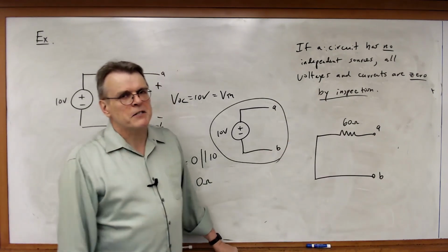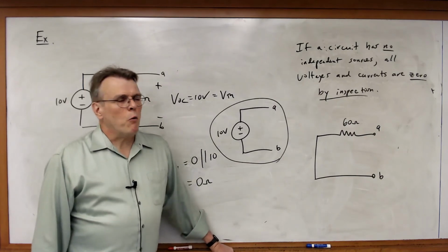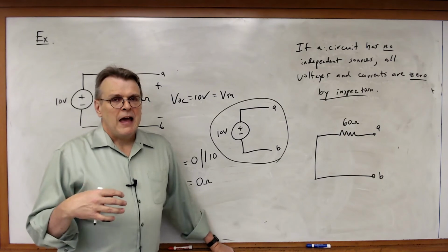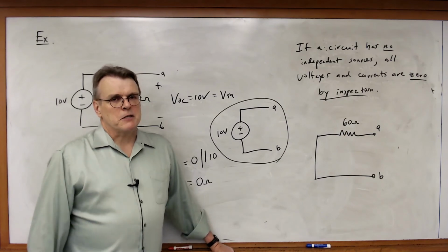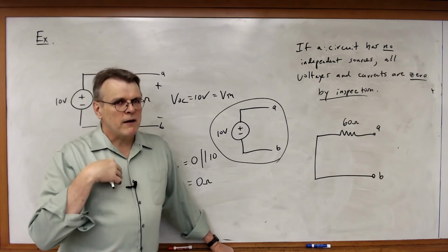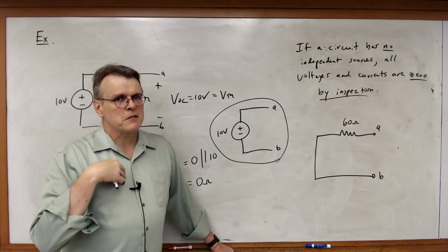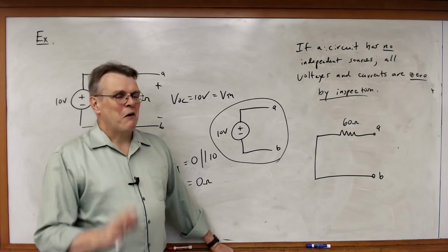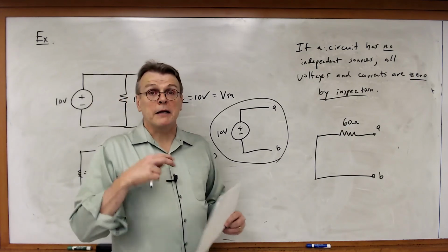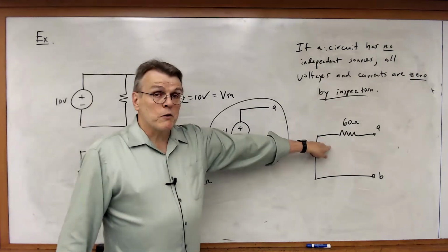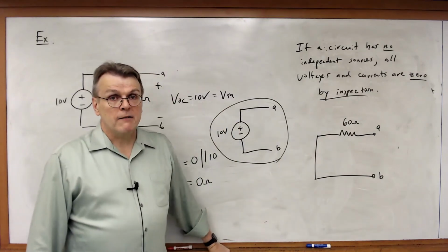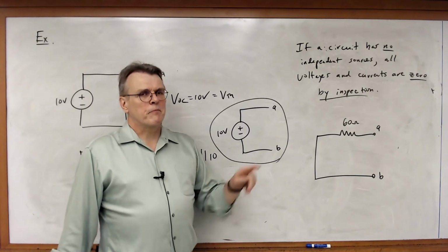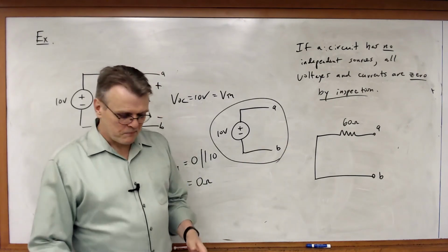But having said that, if you ever work a problem, certainly on an exam, and you get a negative resistance, unless I warn you in advance that there is going to be a negative resistance, then you've probably done something wrong, okay? Certainly on exams that I would give, if I'm going to give you a circuit where you can expect RTH to be negative, I'll tell you, so you'll know it. Otherwise, if you get a negative resistance, look for the error in your math.